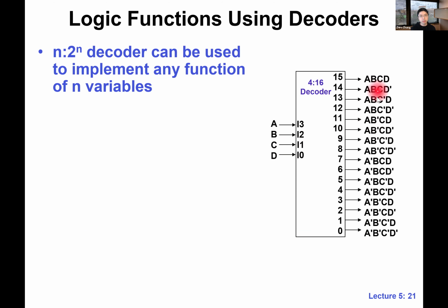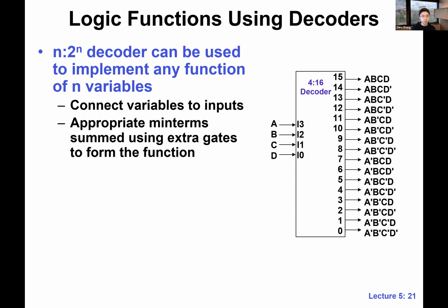We already discussed the property of minterms before, in the second lecture, I believe: given any input combination, exactly one of the minterms will be a 1. The same property holds here. So with this, we can also use the decoder to build Boolean functions, similar to a mux. If we already have a decoder as one of our building blocks, something we have already implemented, we can use it to construct some meaningful Boolean functions as well. So let's see how we do it.